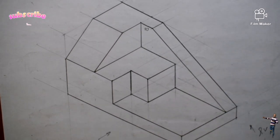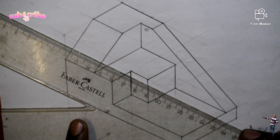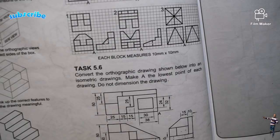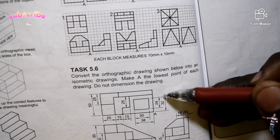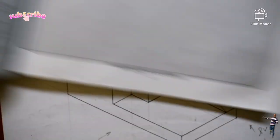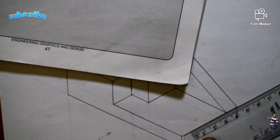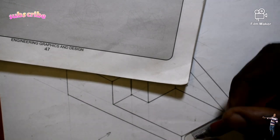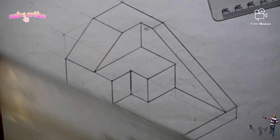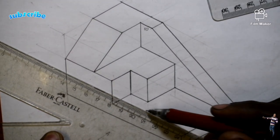You understand? So once I've gotten the 32, I am going to take this line faint. Do you see what they said? From point A coming this side is 32, and where your 32 ends, to go back, they said is 24 millimeter. You understand? So I am going to record my 24. This is 25. There is my 24. And I take this point again at an angle of 30 degrees clockwise as a constructional line, faint. So there you go.